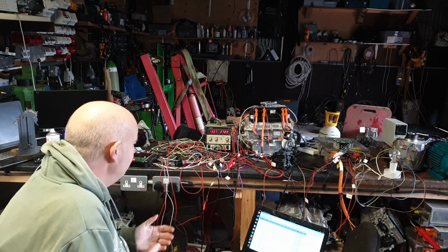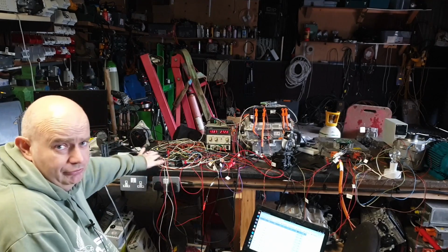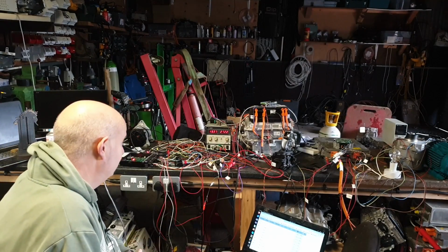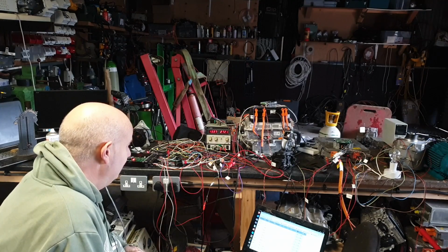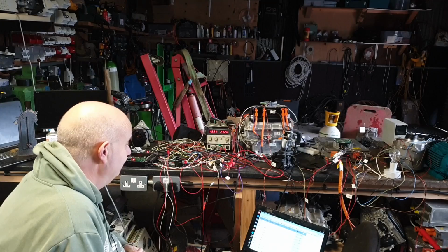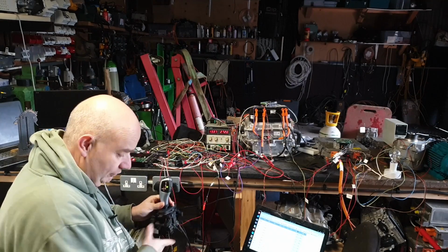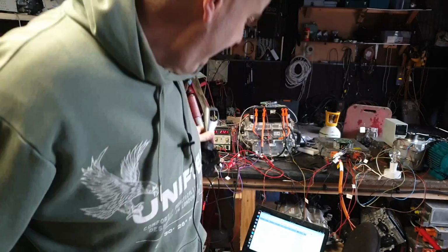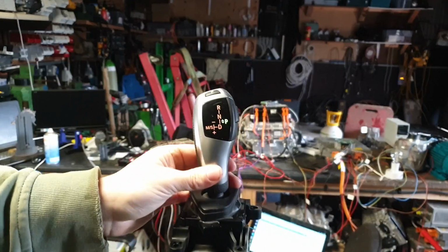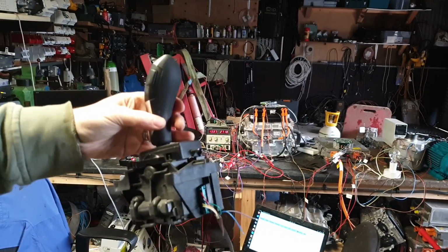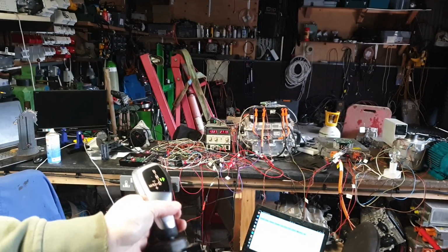The none option basically defaults back to the 2 12-volt inputs that choose forward and reverse. But we've now got a class in there for using CAN-based shifters, such as this guy here, which is our BMW F30 shifter. So this is basically just got 12 volts and CAN, and is talking to our VCU on the bench over there.